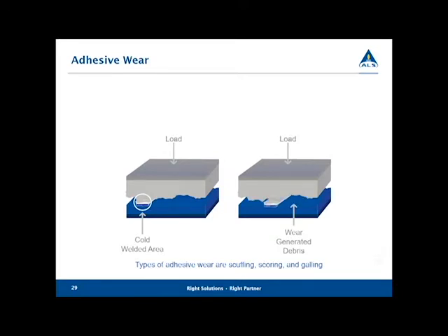Well, that asperity, when it's welded up to another asperity, just isn't going to be strong enough to completely stop that particular componentry from moving. So it breaks off. The weld line stays strong, but the base of those two asperities do break off, and that itself becomes wear-generated debris.